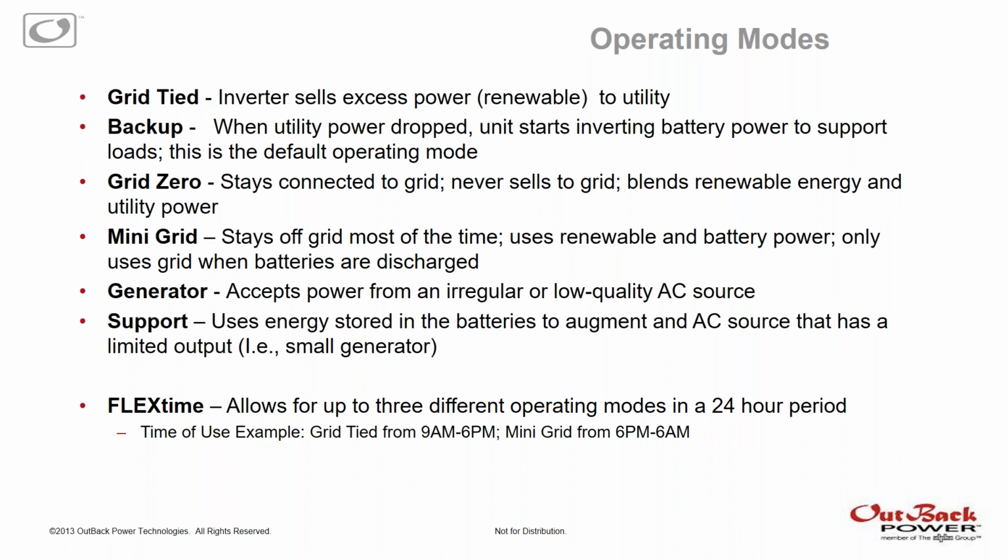The other mode is support. This again could be a great example for what could be going on. If a small generator is available, we can use that generator and help supplement the power from that generator when needed. So if there's larger loads than the generator itself can handle, the inverter can take some battery power, sync up with that generator output, and start larger loads like pumps and motors that need a little bit more power to start that the generator can't do on its own, but with a little help from the inverter they can. So it allows you to, again, use a generator that may not be ideal, but it's available to help support the system.